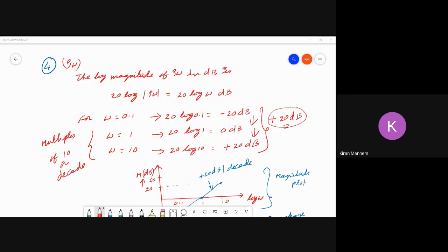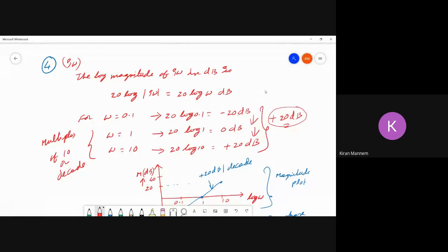Later we drew the Bode plot for multiple poles at the origin, and again a straight line, the magnitude line is minus 20n dB per decade. Phase angle is minus 90 degrees times n. And the third one we completed. Let us take the fourth one, which is the zero at the origin.